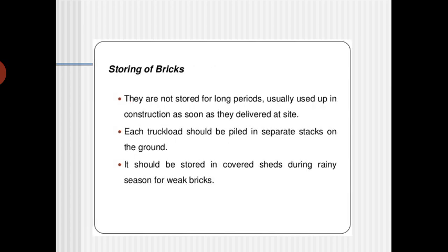So, storing of bricks. They are not stored for long periods; they are usually used in construction as soon as they are delivered at the site. Some types of bricks you can store, but normally we will not store them for more than 6 months. Once you prepare them, they have to be sold before 6 months, because there are many chances that disintegration of the bricks is going to happen.